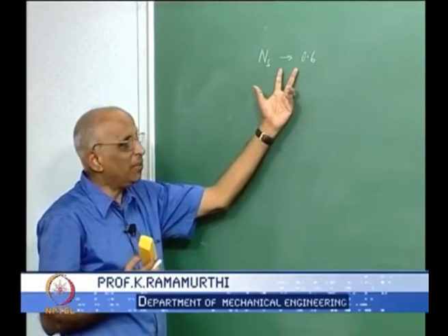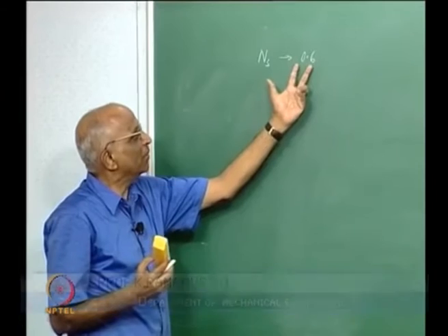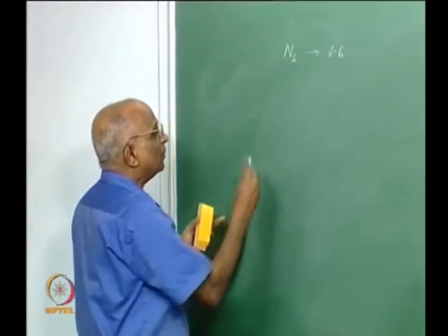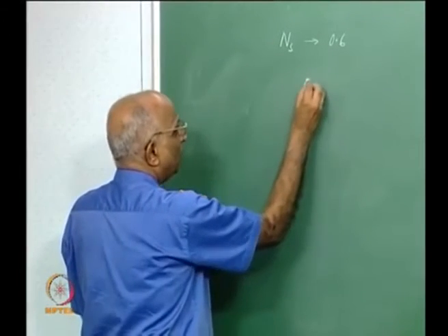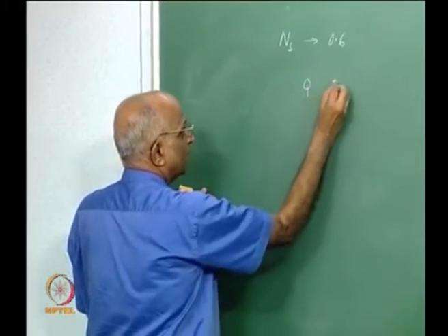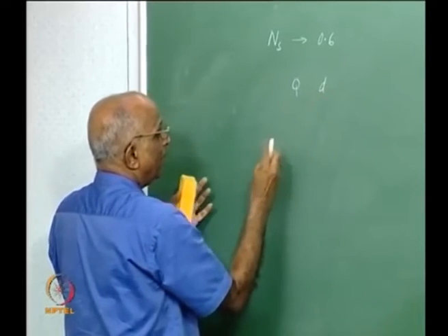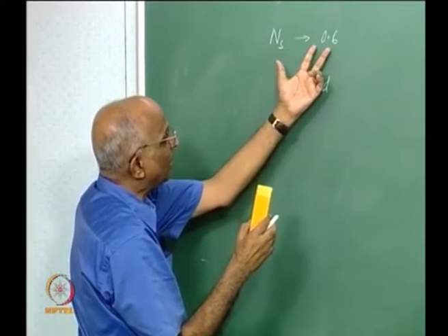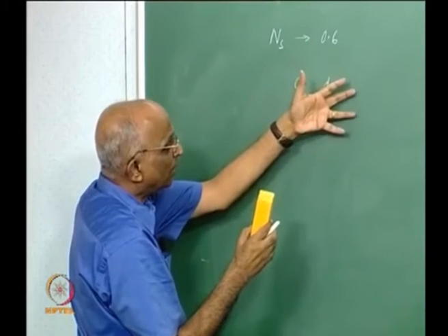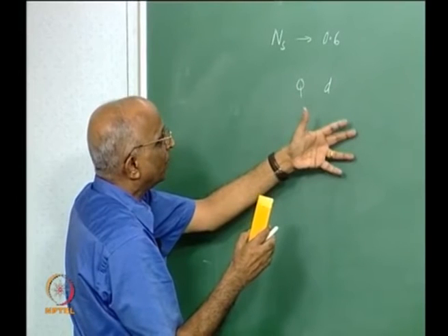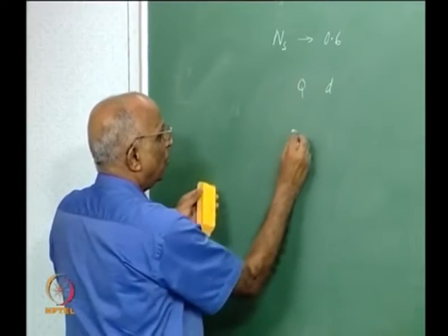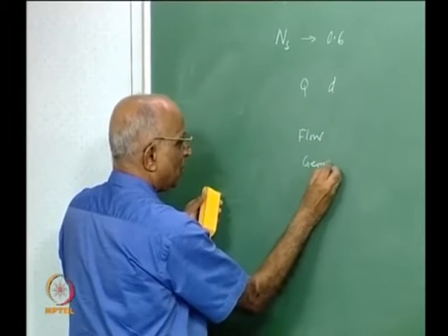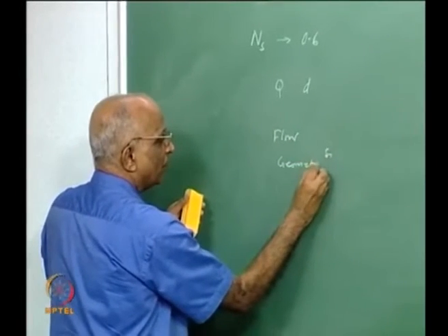This non-dimensional parameter tells me that for a given value of this diameter, if I were to scale up my diameter, I have to scale up the value of Q. All I am saying is that for a pump having the same value corresponding to different sizes and different values of speed, the flow in the pump and the geometrical characteristics of the pump will be similar.